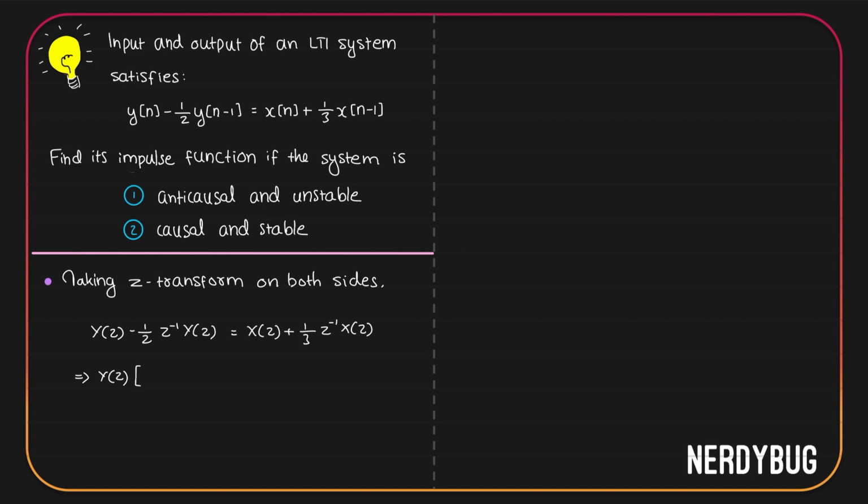On the left hand side, let us take y of z as common. Then it will be y of z multiplied by 1 minus 1 by 2 z inverse. On the right hand side, let us take x of z in common. Then we get x of z multiplied by 1 plus 1 by 3 z inverse. We know h of z is y of z by x of z. So here we get h of z to be 1 plus 1 by 3 z inverse divided by 1 minus 1 by 2 z inverse. Let us split this into two terms. We can write 1 by 1 minus 1 by 2 z inverse and 1 by 3 z inverse divided by 1 minus 1 by 2 z inverse.